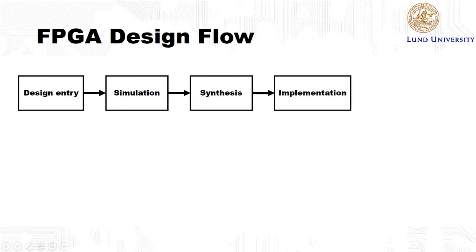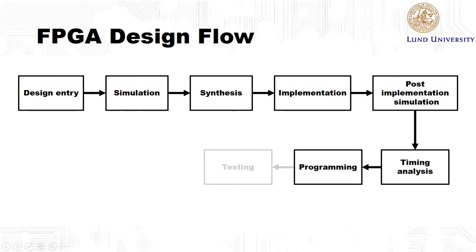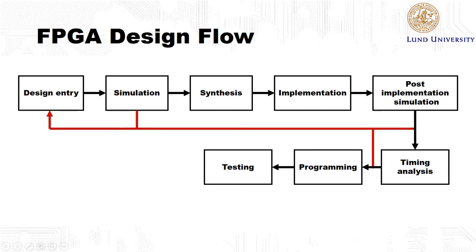Then we run the implementation. Now all the resources get placed in the FPGA, and all the routing is done within the FPGA. After this, we can do another simulation where we also will see all the delays of signals. And we can then analyze if all timings are met in the design. Lastly, we program the device and perform testing on the FPGA platform.